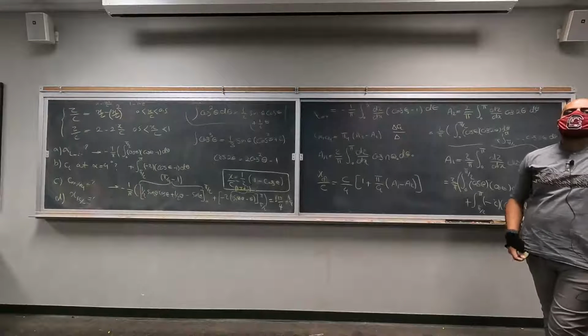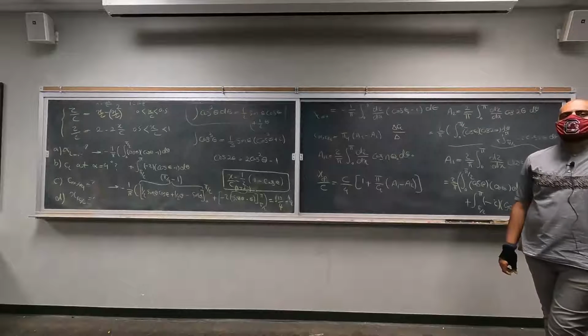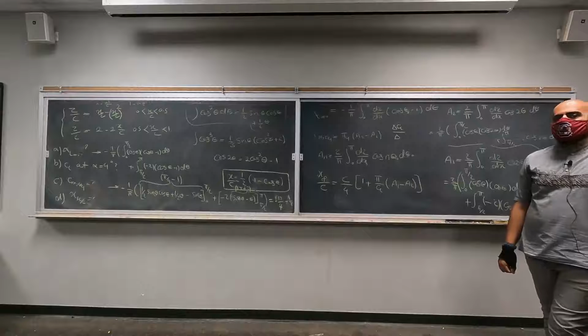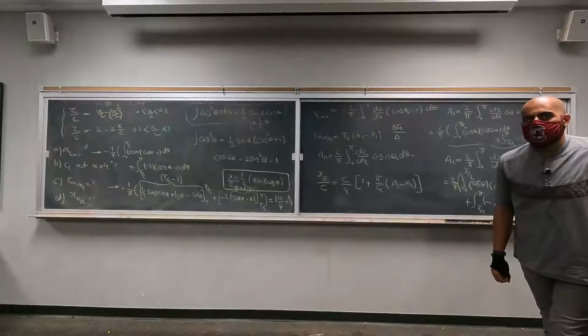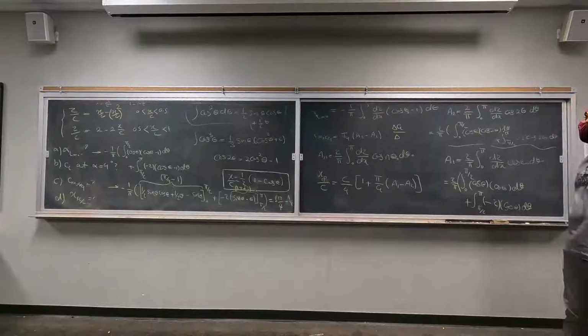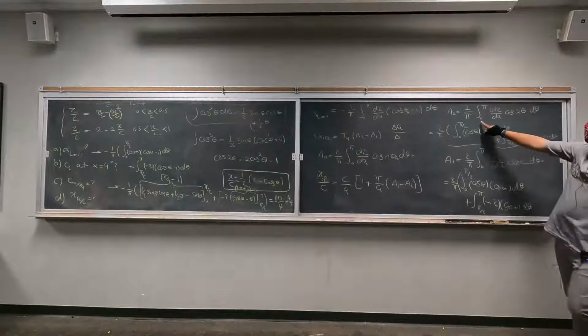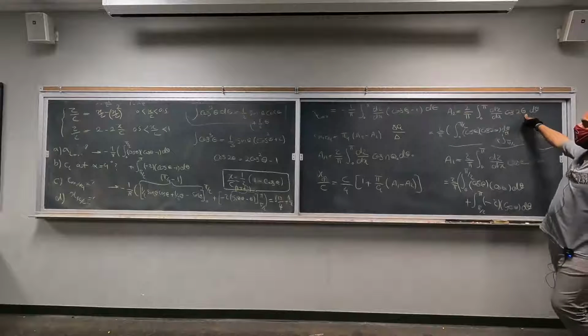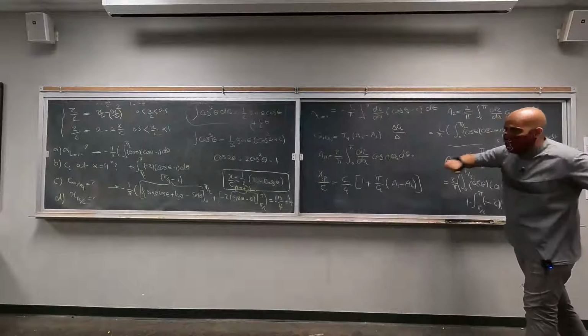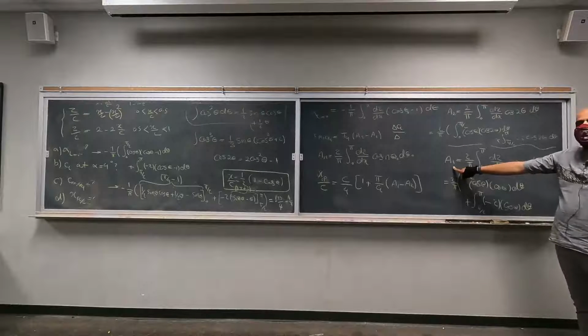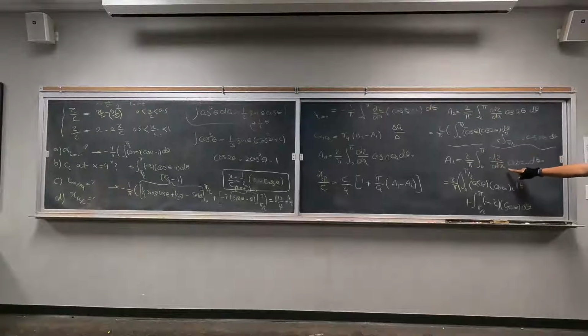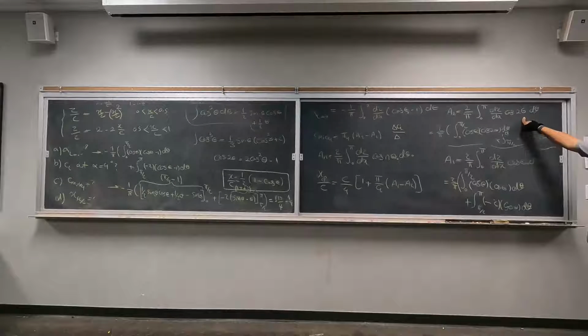Are the formulas for A1 and A2, do they come out to be the exact same? No. This one is the integral of 0 to pi dz/dx cosine of 2 theta, because n is 2. But this one, A1, since n is 1, is the integral of 0 to pi of dz/dx cosine theta. And that means there is a sea of difference between the two integrals. Just make sure that you are careful here.